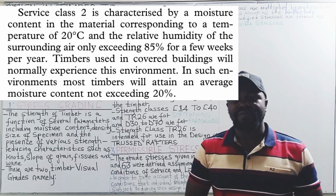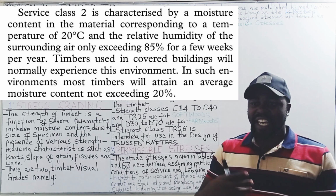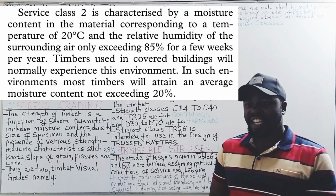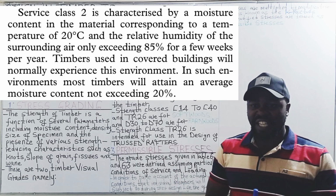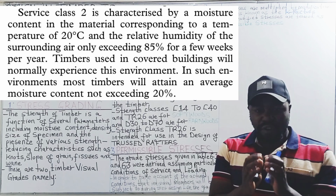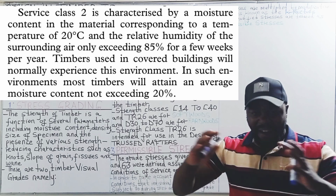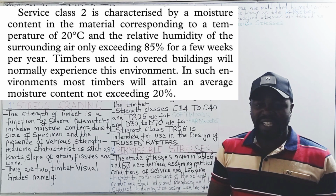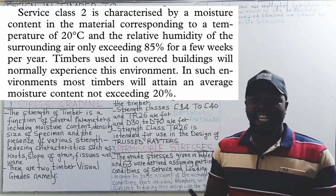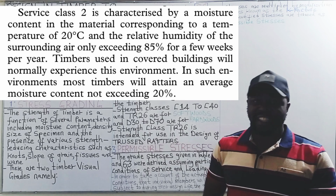Going to service class 2. Service class 2 is characterized by a moisture content in the material corresponding to a temperature of 20 degrees Celsius and the relative humidity of the surrounding air only exceeding 85% for a few weeks per year. Timbers in covered buildings will normally experience this environment. In such environments, most timbers will attain an average moisture content not exceeding 20%.